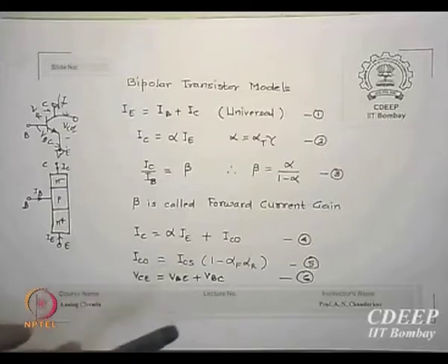More accuracy can be built in, but in circuits, unless said otherwise, the typical currents will be milliamps and typical reverse saturation currents will be in picoamps. So adding a few nanoamps or picoamps to milliamps numerically doesn't matter for us. Physics-wise, if someone objects, how can that happen, the transistor would never work then. That's not our idea. The idea here is the number, and therefore to some extent we will bypass such small values.